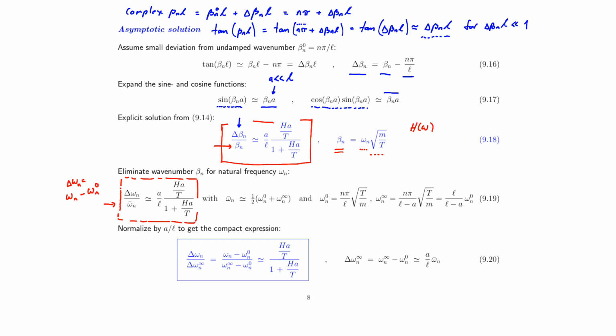So once we have the solution for delta omega_n, we will actually be able to find the full complex natural frequency by this solution delta omega_n when we add the undamped natural frequency. So although the expression in 919 is not formulated in terms of omega directly, but only in terms of its increment with the delta, it's quite easy afterwards to find the full complex value by simply adding the real valued natural frequency without damping that is given here in the second term of this expression.